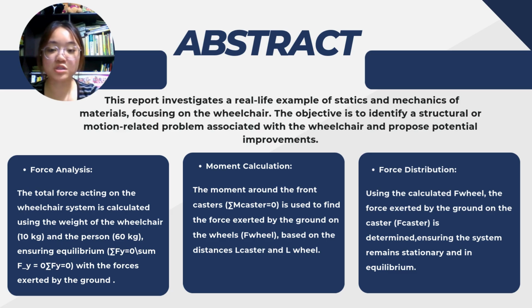For the force analysis, the total force acting on the wheelchair system is calculated using the weight of the wheelchair, which is 10 kilograms, and the person, which is 60 kilograms. To ensure equilibrium, we are using the formula total Fy is equal to 0, with the force exerted by the ground.